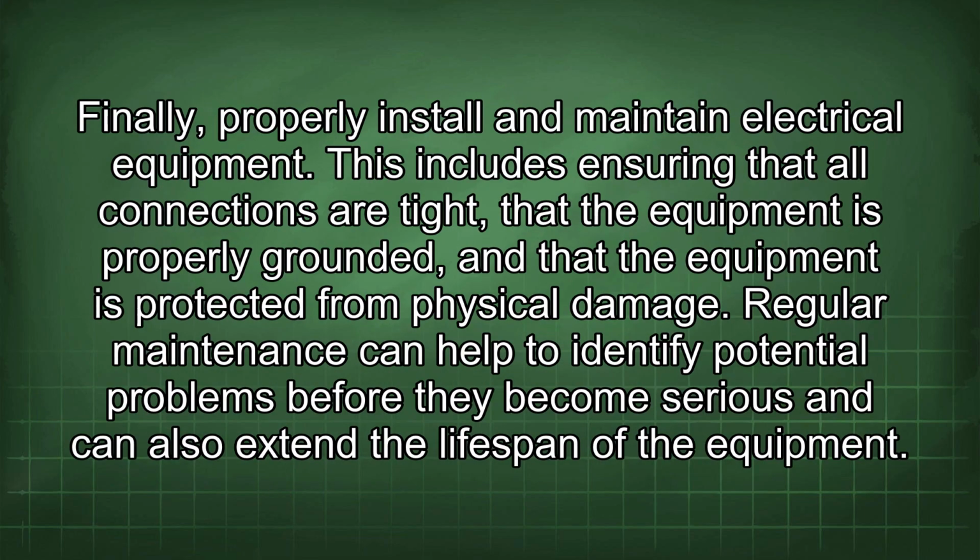Finally, properly install and maintain electrical equipment. This includes ensuring that all connections are tight, that the equipment is properly grounded, and that the equipment is protected from physical damage. Regular maintenance can help to identify potential problems before they become serious and can also extend the lifespan of the equipment.